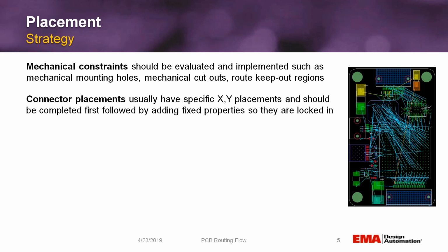Next would be your connector placements. Usually these have very specific locations because other devices plug into these things, so they usually have a specific place that they want them located, and once they're placed, you should lock them down with a fixed property so they can't accidentally be moved.